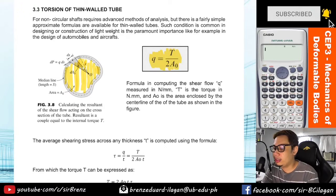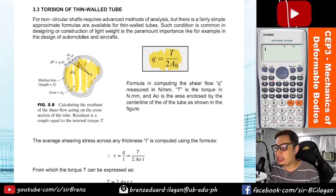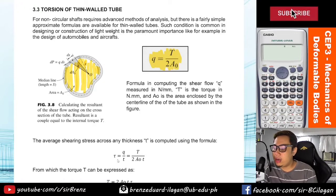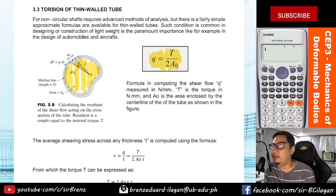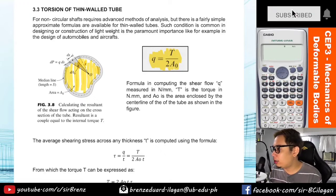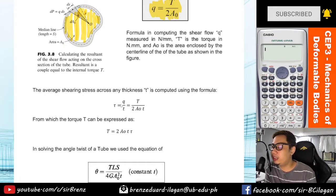So, the average shearing stress across any thickness t is computed using the formula where the shearing stress tau is equals to q, the shear flow, over t. Before we proceed with this equation, again, ang unit natin guys for shear flow is Newton per mm. Okay? Given by the formula, again, shear stress is equals to shear flow over the thickness t.